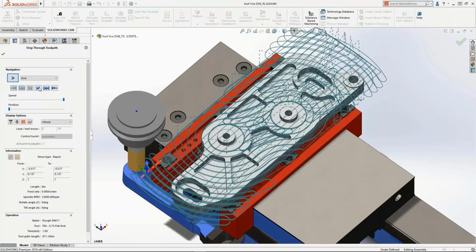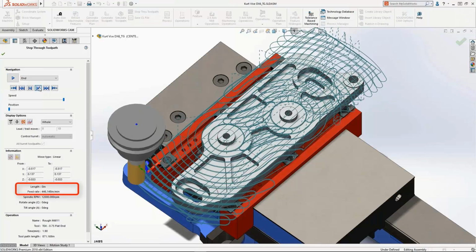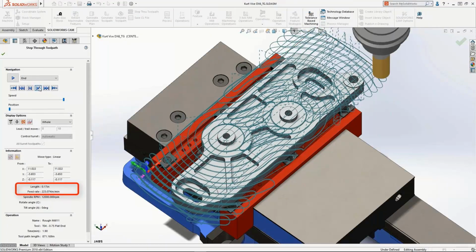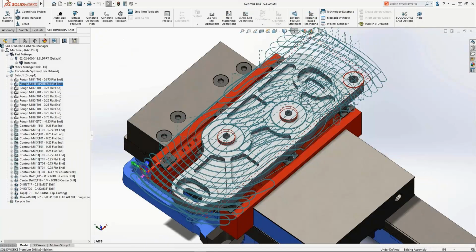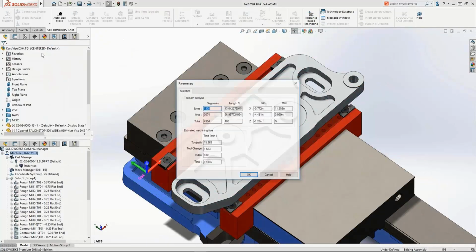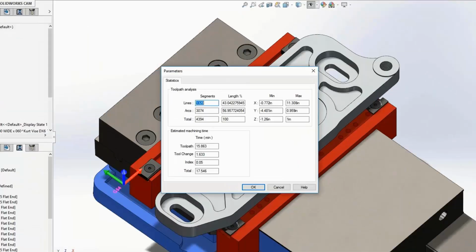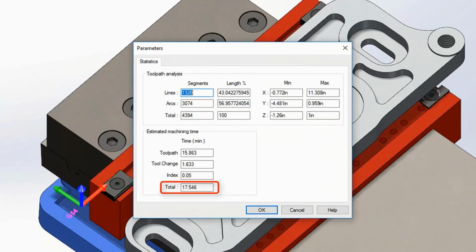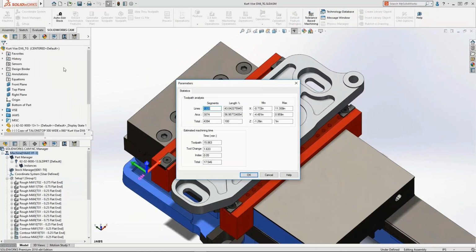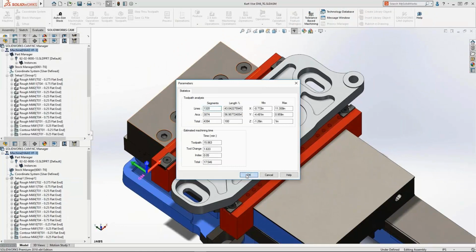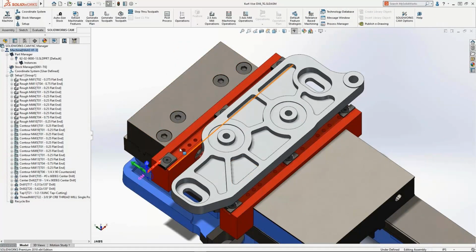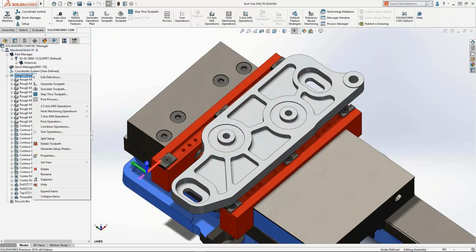If we look at the tool path, we'll see again how the feed rate is constantly changing to make sure that the tool has the best possible working environment. And this entire program went from 42 minutes to 17.5. That's a huge saving. Imagine you're doing 10, 15, 20 of these parts. That's hours and hours of machining time we just saved by applying high-speed technology to this part.